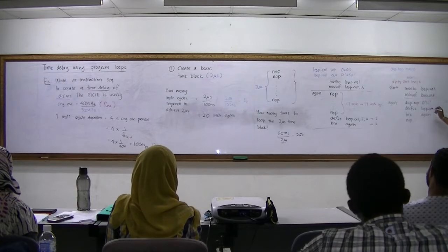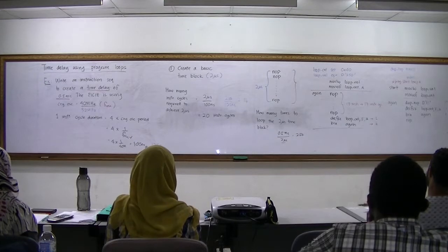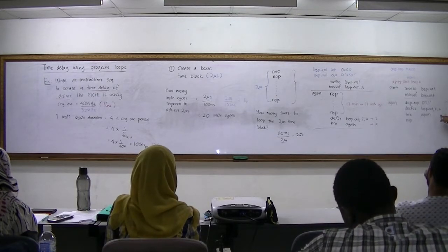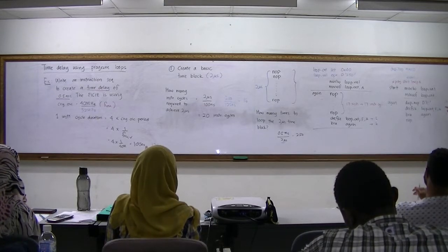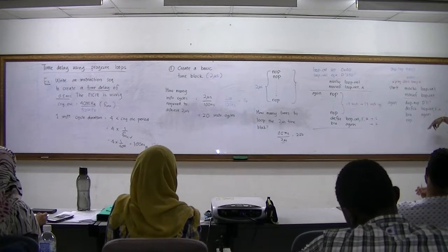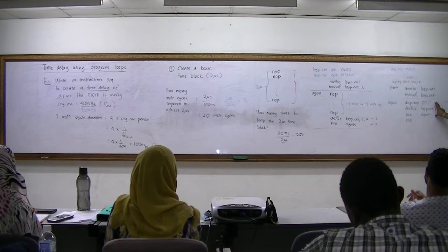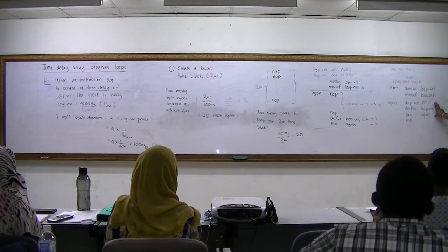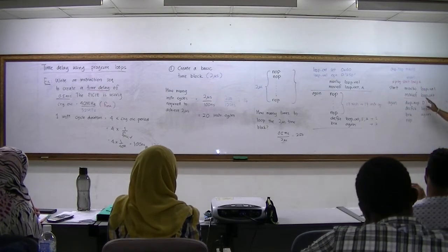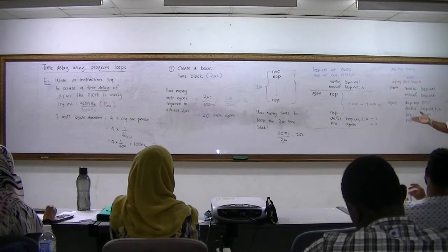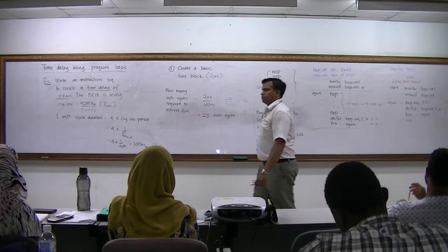Always remember, the total number of instruction cycles must always minus 3. Why? Because of this and this. Always minus 3. So this is 13, 14, 15, 16. We have 16 cycles. And you loop it 250 times. This 16 cycles generates 2 microseconds because this is based on 32 megahertz frequency. And if you do this 250 times, you get 0.5 milliseconds. Is that okay?